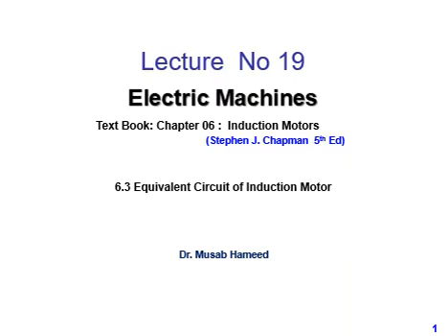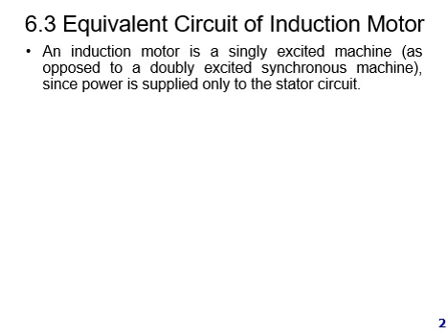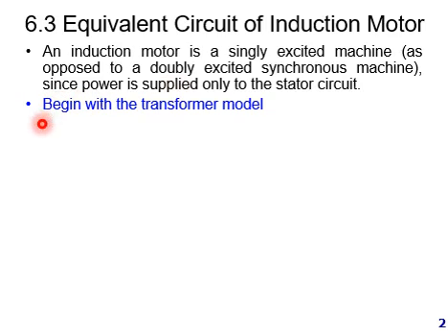Dear students, in today's lecture we will study the equivalent circuit of induction motors. An induction motor is a singly excited machine, unlike a synchronous generator, which is a doubly excited machine, since power is supplied only to the stator circuit in this case, not to the rotor circuit.